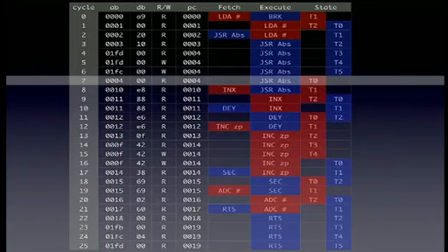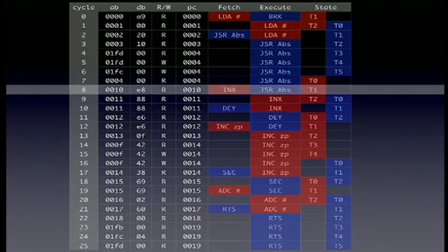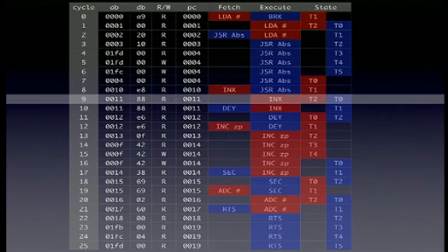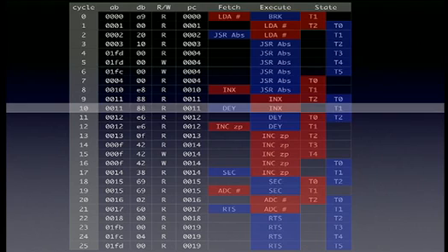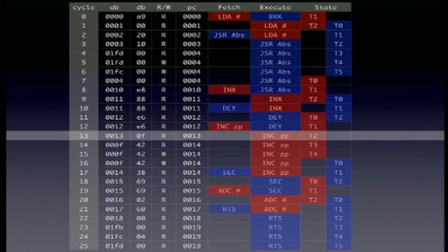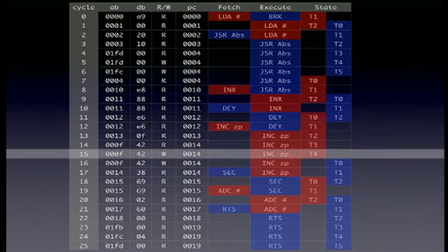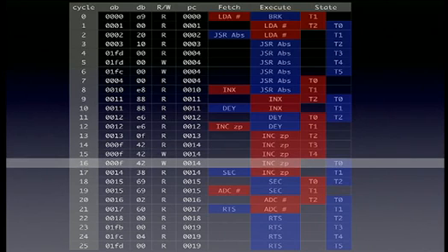So in this example, you can see here, the jump to subroutine is not even finished, but we are in T0, in the first stage of the next instruction fetch already. Here we are in the decode of the INX instruction. Here we execute the INX instruction, but we've already fetched the DEY instruction, which is the next one. So there's quite some interleaving going on there. Not in this case, though, if you look here, because the INC instruction has to write back out into memory in its last cycle, so we cannot fetch the next one at the same time already, because memory is already used, so you don't have overlapping here. So this is done really, really efficiently.